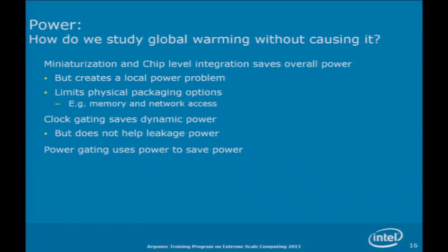Power gating is where you actually turn off the whole function that you're not using. It's more effective, but now you consume power to save power, assuming that you bought this computer because you wanted to use it. It's sort of annoying to have these power gates sit there consuming power and never really turn off.